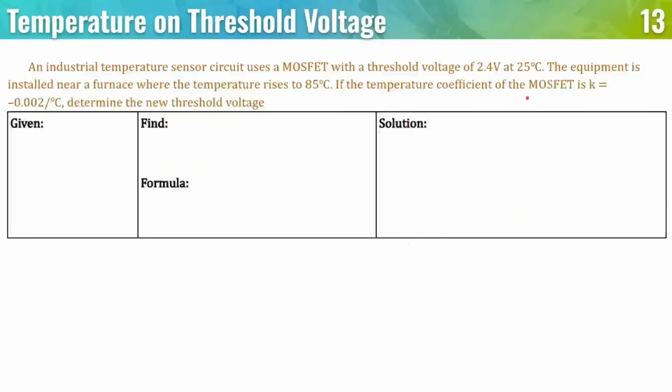So now with the given, let's focus here on 25 degrees Celsius. In a lot of textbooks and even on YouTube, 25 degrees Celsius is specified as room temperature, and you may be familiar with the thermal voltage of 26 millivolts. For the purpose of our examination and per the instructor's instructions, we are not to assume 26 millivolts right away.